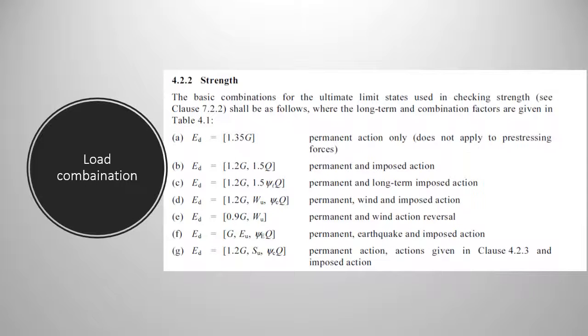For the wind load, we just need to use the data from the previous calculation from purlin design and calculate the total wind load for both pressure and suction. According to the equations in AS 1170.0, section 4.2.2, we could use these equations to find the most adverse combination. In other words, it is to find the maximum compression and tension force.